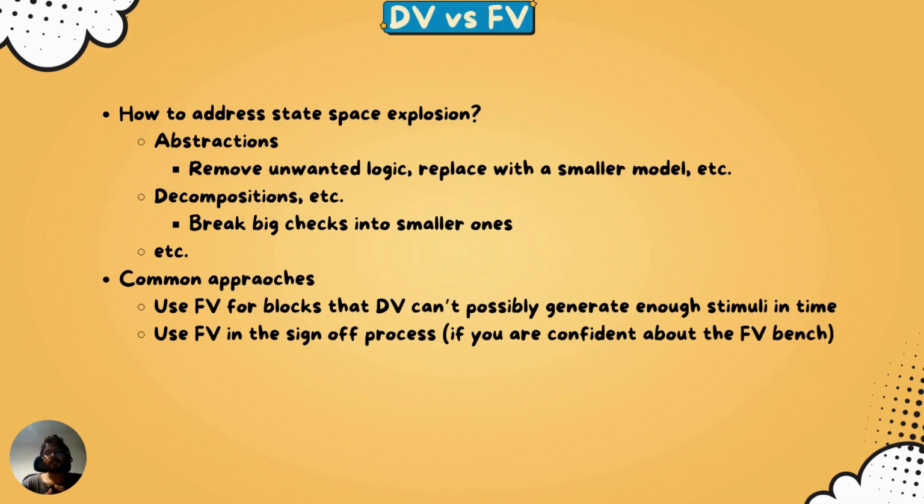There is another concept to remember: bounds, or clock cycles. Simulation runs for a certain number of cycles covering a particular test sequence, and formal works on the concept of bounds. Let's say you have a property and it did not fail for bound or cycle 10. Then the only guarantee you can give is that if the system is starting from a particular specified state, and it is run for 10 cycles, or goes to a bound of 10, there will not be any bugs. That guarantee is what you can give. You cannot give any guarantee that there will not be any bug after that.